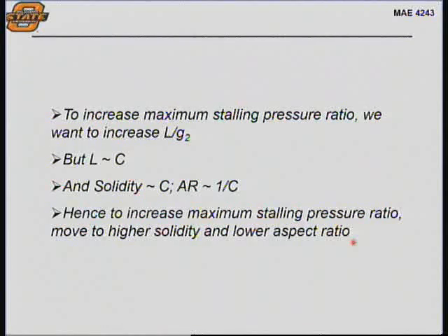And indeed, this stall margin correlation became a design practice, and that's why the GE90, which was based on the E cubed, had a pressure ratio of 23 in just 10 stages, versus say the J79 compressor, which had a pressure ratio of like 13, but it took 17 stages. And if you go back and look at the blading, you will see very evidently that you have the differences in solidity and aspect ratio between those two.